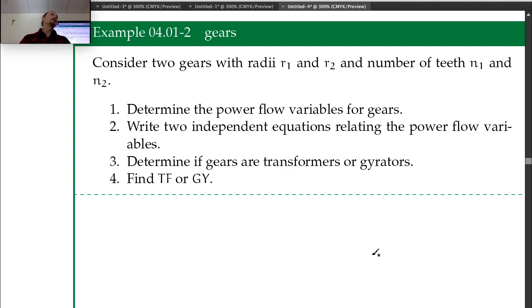You need that torque sometimes to be higher than it is. So you're willing to let your motor run at a high speed and have your load move at a lower speed to get some more torque, which is really common for a lot of automation things. You have a motor that is better to run at higher speed, but you've got to gear it down so that it moves the load at a lower speed.